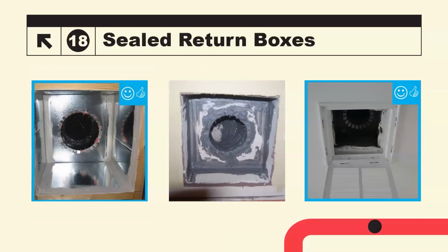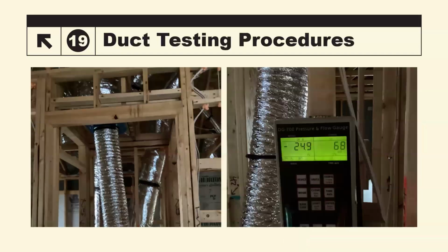Yeah, in this case, yes, that's duct board that you're using. So it's basically a crushed, kind of hardened insulation, and the box is being made out of duct board. And as we see, if you're looking at fibers, air can move in and out of that insulation. So good point, good catch on that. If you've got a breathable material like insulation surrounding these boxes, in my opinion, they should also seal those fibers up. You should just be seeing the flat surface of the insulation. Good point. Thanks for the question.